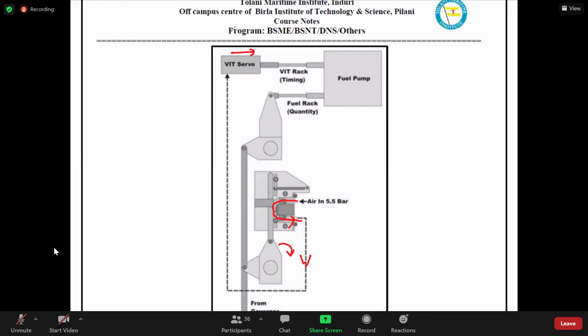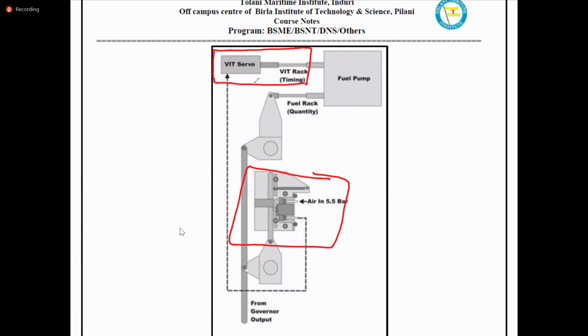Yes, sir. So the governor will come into the picture, and the correct setting, the correct calibration of this valve and of this VIT servo, these two are very important factors. If they are not set correctly, the VIT cannot function correctly.